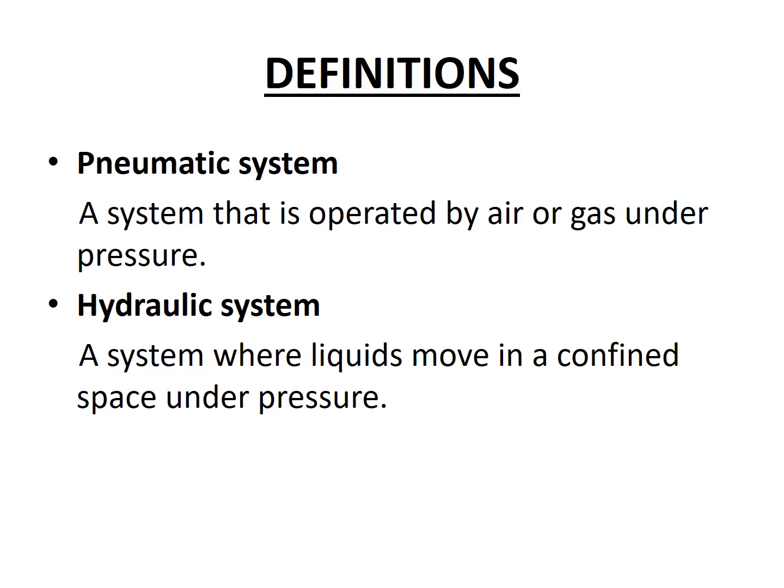These are the differences between the two. Pneumatics use gases, whereas hydraulics use liquids. And very importantly, we're not saying hydraulics use water, but we're saying liquids, because in most machines they use oil as compared to water. And hydraulic systems do have some advantage over pneumatic systems, because for the fact that liquids cannot be compressed, they give us a better force.